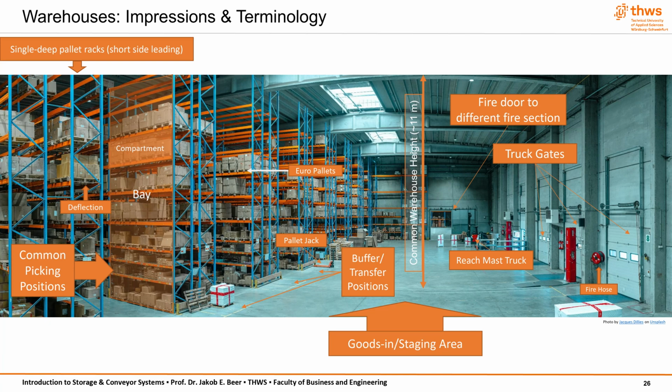It's important to note that the rated racking load of a pallet is not the same as its static or dynamic load capacity. Only pallets explicitly rated for racking should be used without additional support. And finally, pallets should be inspected regularly. Over time, even high-quality pallets degrade, especially if they are reused frequently or exposed to harsh environments. Damaged or deformed pallets should be removed from circulation to prevent accidents and maintain system reliability.